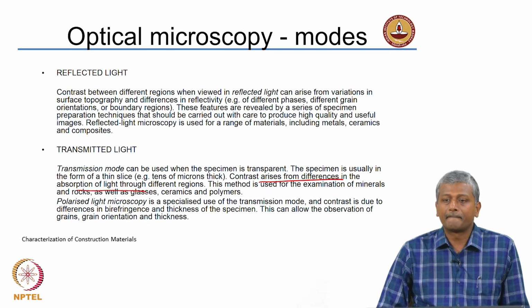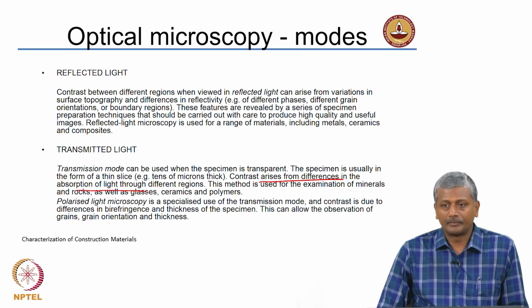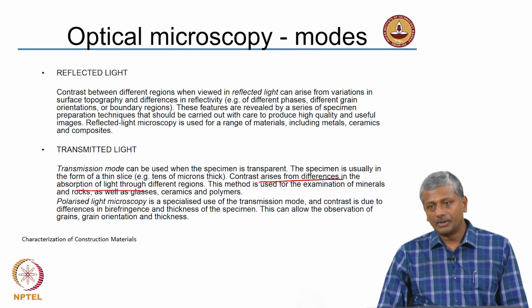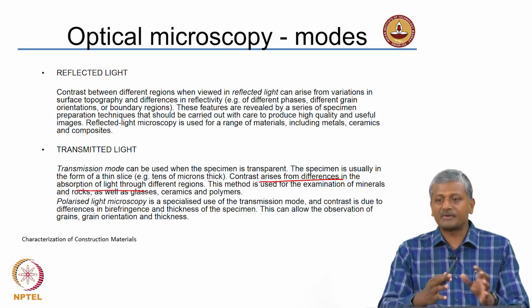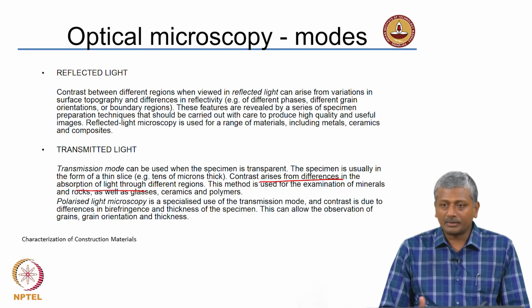Yes. Sir, in the case if you want to study the mineralogical composition of the specimen, yes, you have to do transmission optical microscopy. We do not have any accessory items to help us identify the mineralogical composition. So, how you identify a specific mineralogical composition is by comparing a material of several phases with certain known phases, right. You cannot arrive at a conclusion.